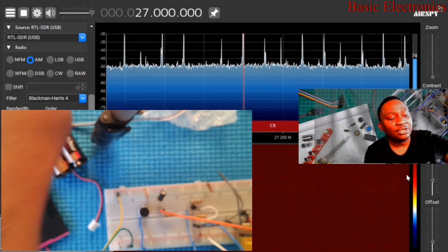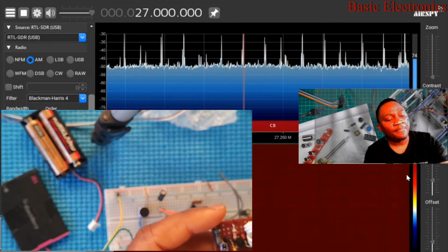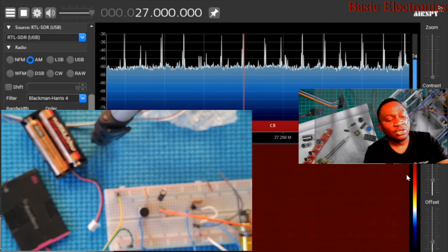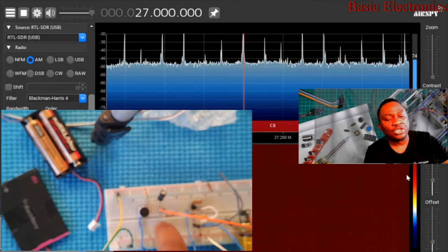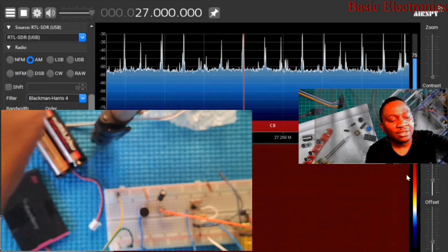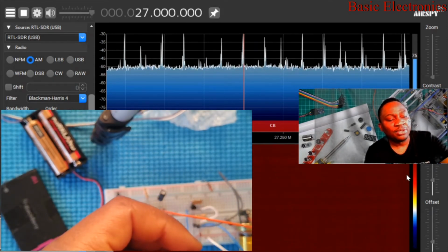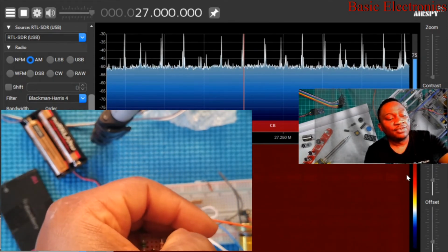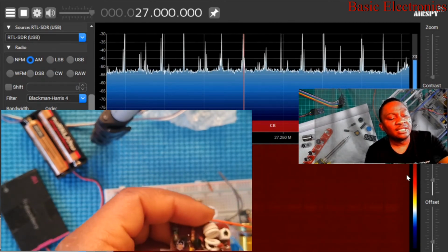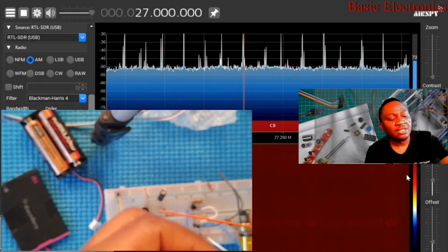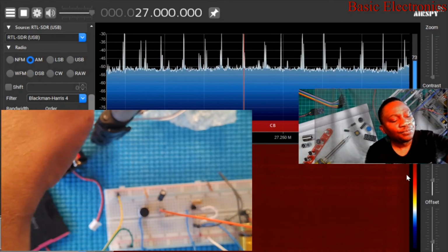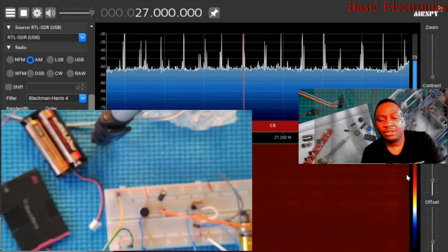We have shown you how to build an FM receiver using just one transistor. You can build that out and then build this transmitter, with its stable frequency. Make sure that the resonant frequencies correspond, and using a tuner, a variable capacitor, you can tune to this frequency. Remember, what you need is the inductance and capacitance to correspond to the resonant frequency of this crystal, and that will be it.